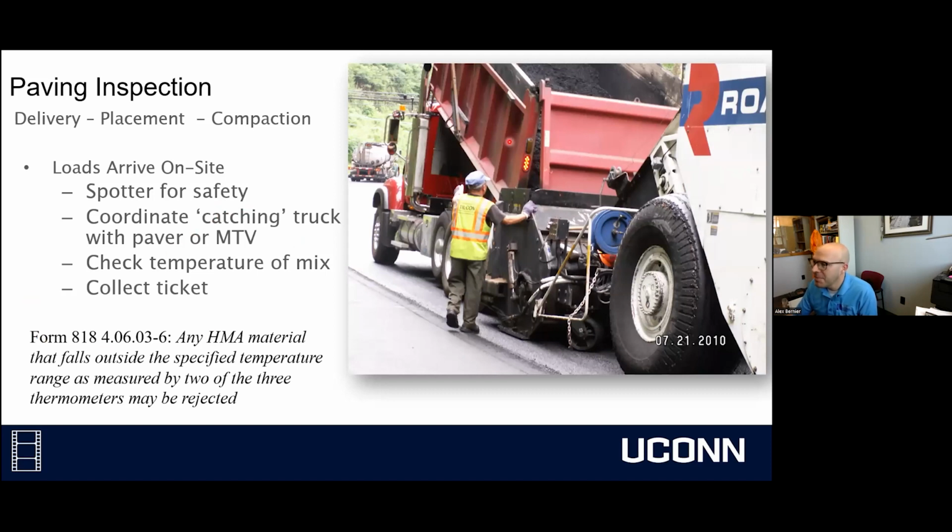They're going to check the temperature, and they're going to collect a delivery ticket from that truck. So every truck that leaves a plant has a ticket with them. And that ticket tells you what project it should be going to, and the time and day the material was loaded. It's going to tell a whole host of things. And I have an example ticket coming up.